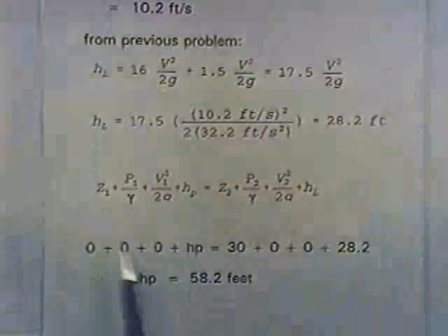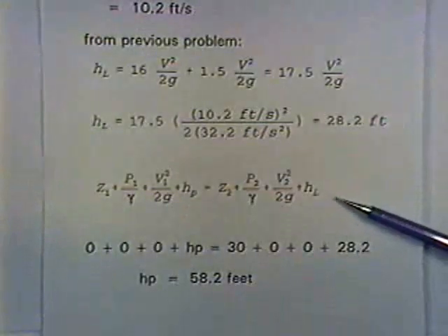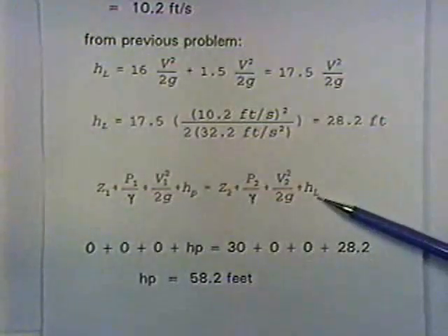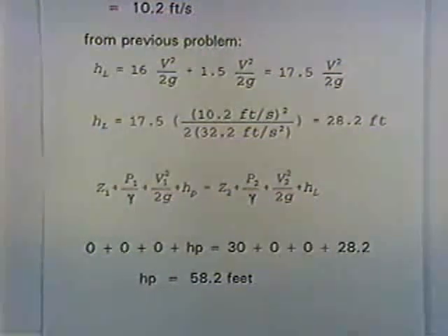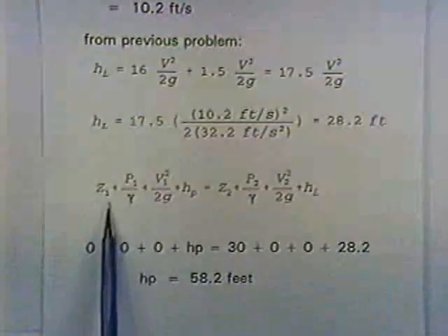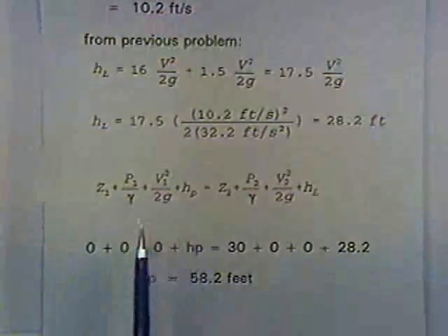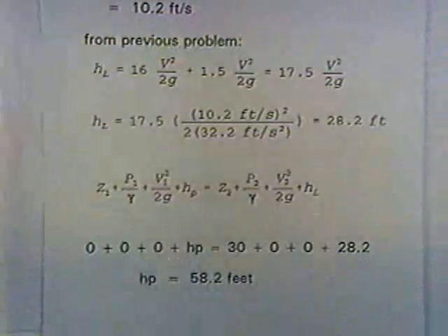And our old friend, the energy equation, which we use over and over in hydraulics. And we plug in our estimate for the head loss, and we plug in everything else. We're going backwards this time. So I'm letting subscript 1 be the downstream reservoir, which is on the right in the figure. Subscript 2 be the upstream, the higher reservoir, which is on the left in the figure.